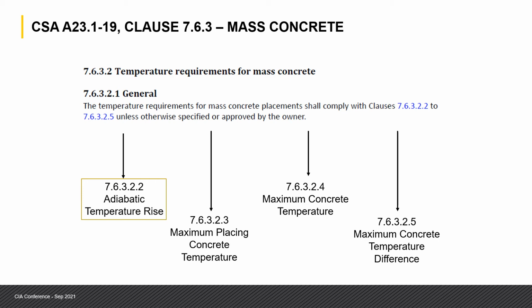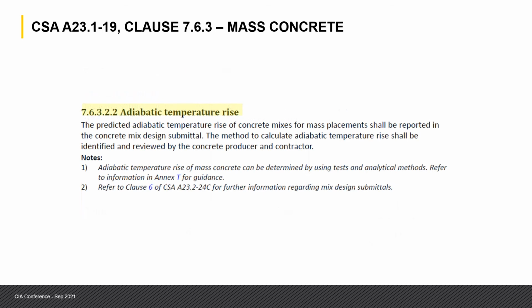So what happened in Canada first is that we don't have a good description of the mix proportions. So for the thermal control engineer, you typically do not have that information readily available. So we need to first assess adiabatic temperature rise as a property we need to consider. Now, what did we do? Pretty much we put a requirement to ensure that we qualify the ability to generate heat by the mixes.